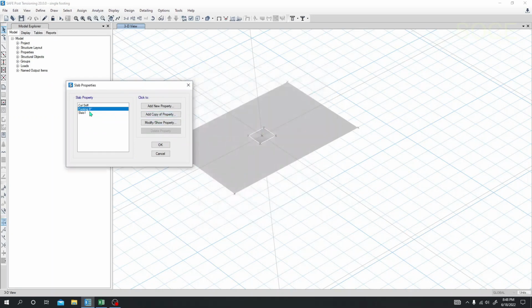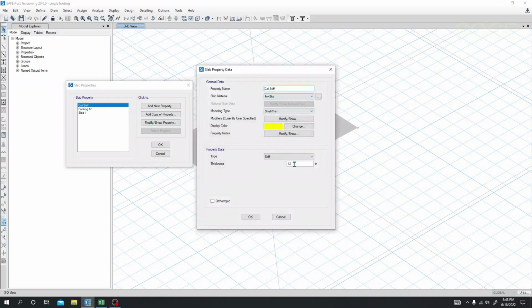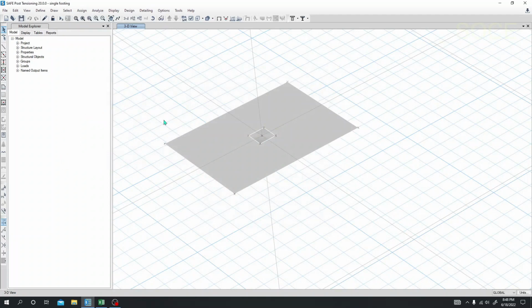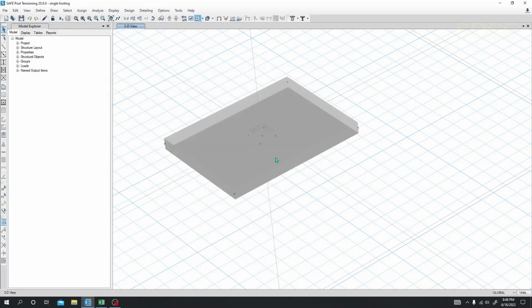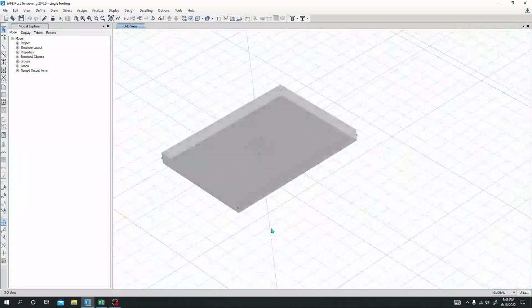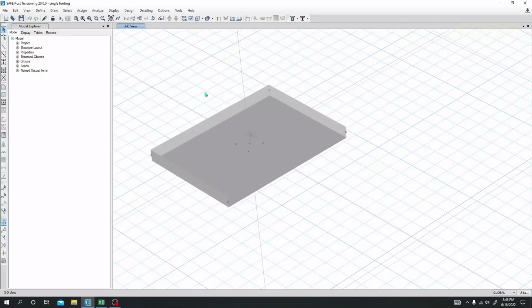Okay, and for column stiff also it should be 8-inch column stiff. Then okay, after that, if I just go extrude view, here in our extrude view, so when it's done, again I'll go here, run analysis, and we'll see what happened.